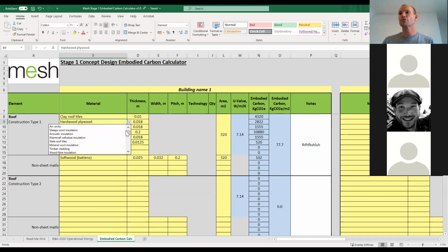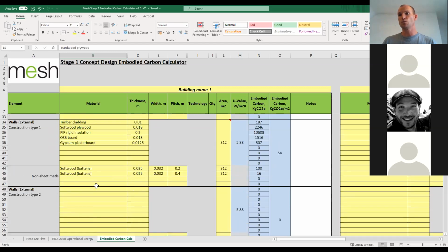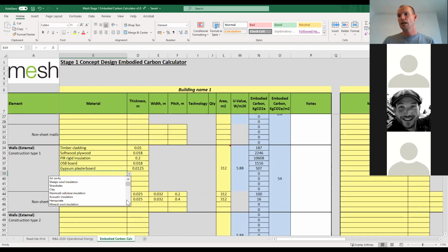You have got materials, for example, I added here the other day, some pretty good alternative materials. If we just have a look at walls, I'll give you an example. We've got clay, we've got straw bales in there, we've got hempcrete, we've got adobe. Say adobe, for example, which is a kind of clay brick material. There is a variation on the lambda values for that. So again, we've picked a mid-range value, but invariably, depending on the final type that you choose and the final makeup of that, that lambda value may well be different.